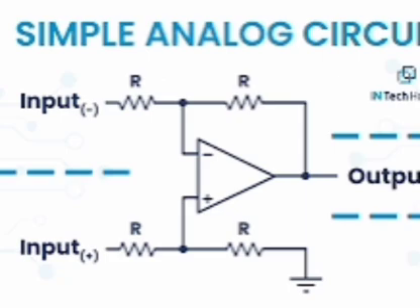Advantages: self bias circuit has the least stability factor among all biasing circuits. Stability factor is independent of RC. Self bias circuit can be used to bias BJT for any configuration. Drawback: resistance RE creates negative feedback, due to which voltage gain V0 by Vi or V0 by Vs becomes smaller.